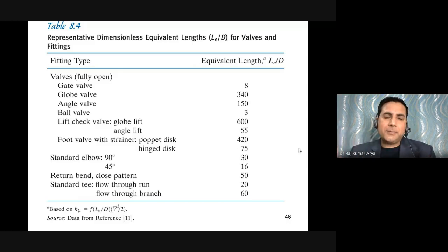Now you are connecting them. To connect them, either you put a weld. Welding is one thing. If you put a weld, then in case of failure you will not be in a position to take out a particular segment, so you have to cut it down and join it. That creates a problem. So welding is a permanent type of joint, which creates a problem in case of failures, because you cannot take out the segment easily. So you put a socket.